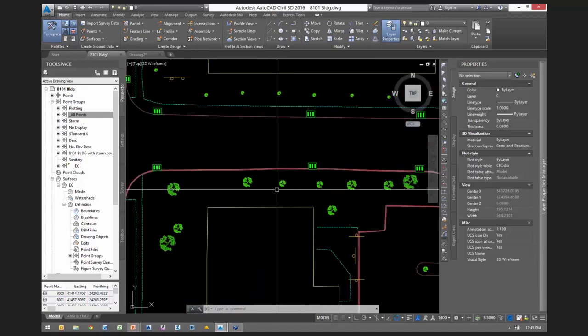Okay, so this works great. So you might be saying, well, what if I extract this into one drawing to make a 20 scale sheet and then another drawing to make a 100 scale sheet, and I have one description key set for both of them? You're right, it doesn't work. You have to have separate base files. Description key sets, styles, point groups, none of that stuff pushes through an XREF. All you end up with is layering.